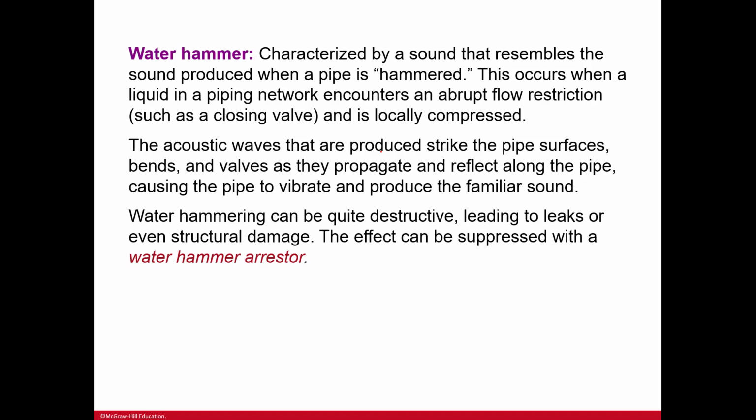That's similar to what's happening here, but because we're working with liquids and not air inside the pipe, you experience an acoustic wave, and it strikes the pipe surfaces, bends, and valves as it propagates and reflects along the pipe. And so it causes that vibration.